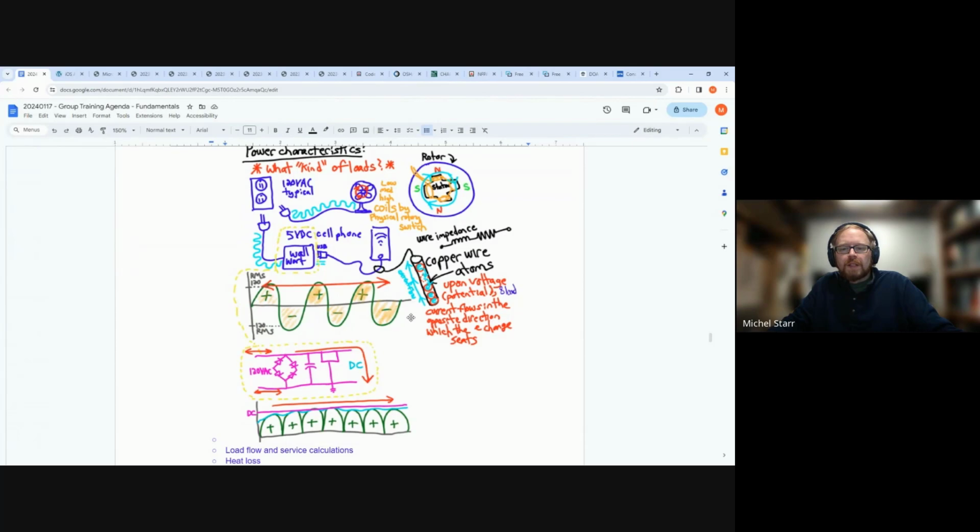Could also be an electronic one, like a variable frequency drive, such that it is changing from AC to DC, and then on the output, recreating by pulse width modulated signals the sine wave, to make it look like a sine wave enough. You then control the speed by varying the frequency, the frequency being how fast, 60 hertz. So how many times per second is it alternating?